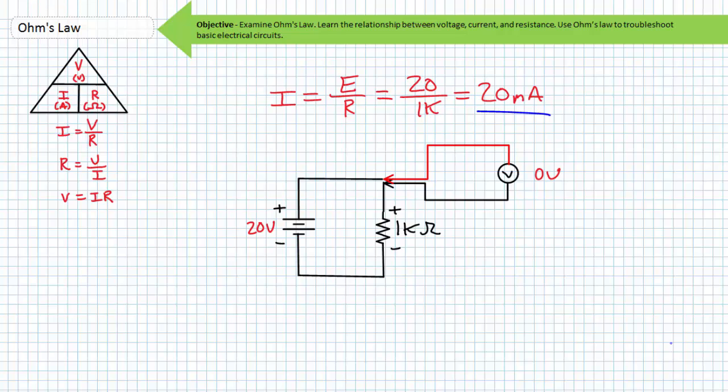Instrumentation errors are the most nefarious of errors, and largely the ones I hope to permanently abolish with a lab practices lecture accompanying this playlist. You simply must know how to use common instrumentation to take valid observations. Even if your circuit is functional, you can't get good readings if you're using your DMM incorrectly. Again, voltage is a 2-point measurement across something. If both leads are measuring the same point, there is no differential between them.